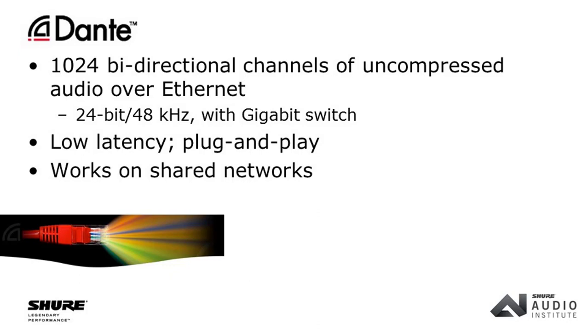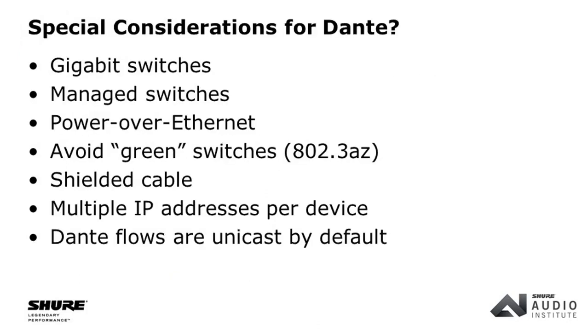And this is a real advantage to Dante over some of the prior network digital audio protocols that required their own standalone network that had to be completely separate. Even though it was using standardized Ethernet hardware, it had to be its own thing. Dante can exist on your corporate network and doesn't interfere with your web browsing or your email or any of that other kind of stuff. It actually is a really good solution for that reason.